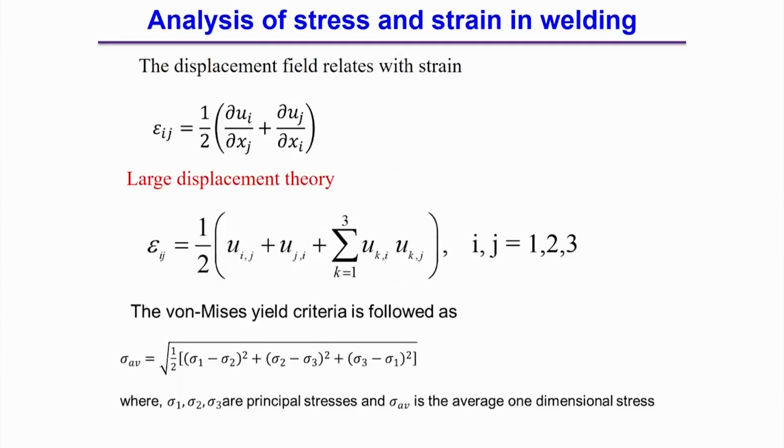The displacement and strain field are related by this equation. This is a linear relation between the strain and the displacement component, but that is called the small displacement theory. That means, in this case we normally neglect the nonlinear term of the distortion, and then we simply relate the stress and strain this way.